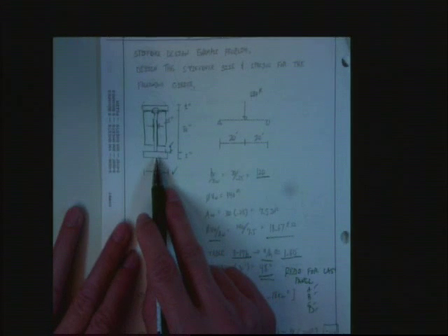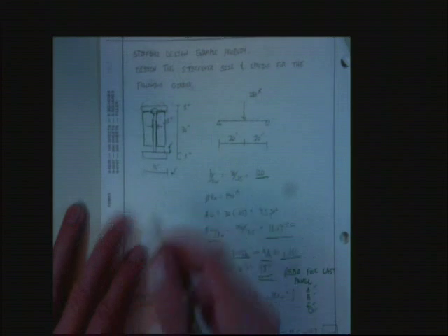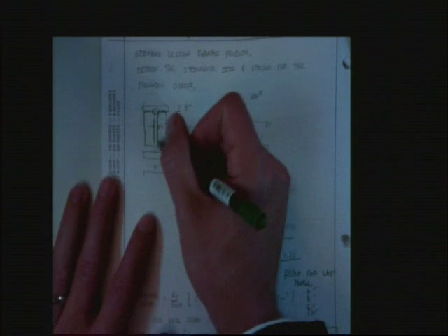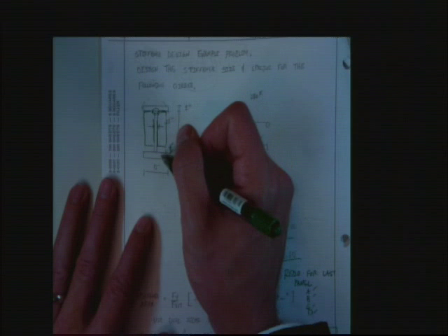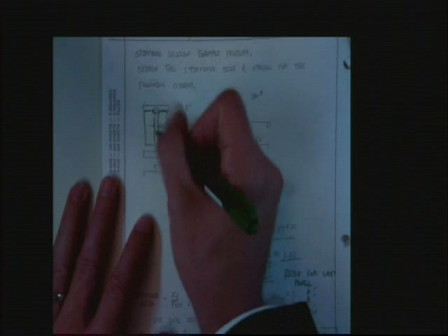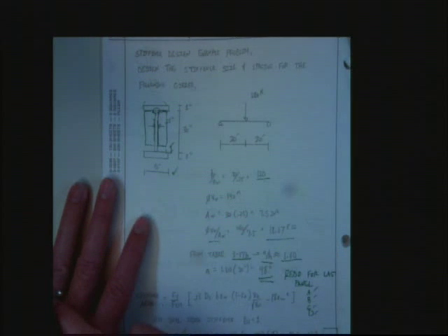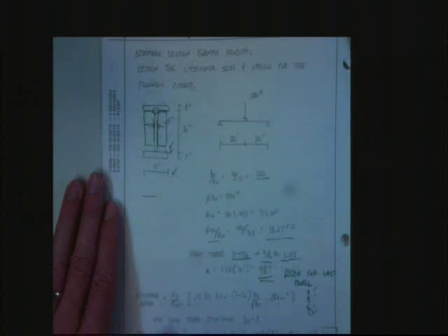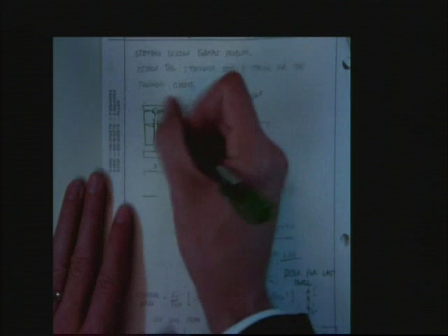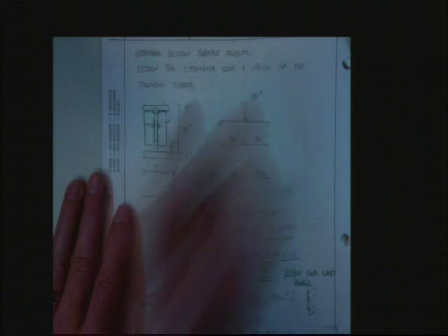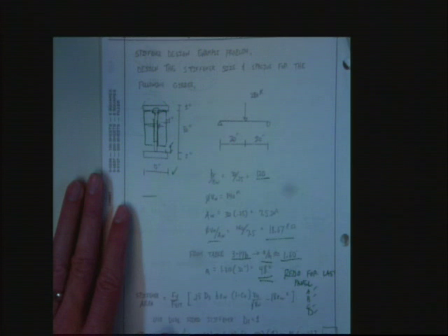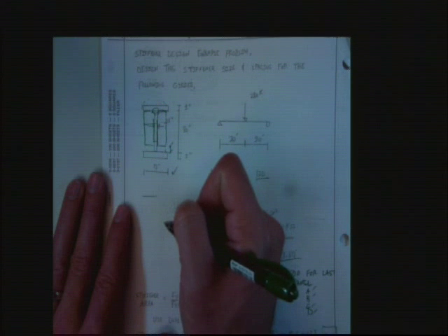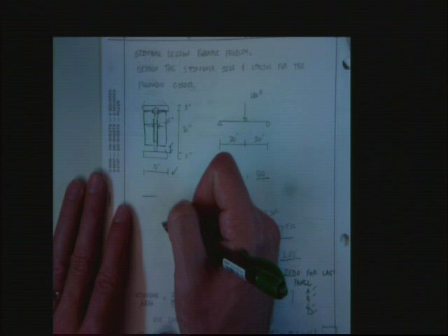Now, was there something else people wanted to say or ask about this? You asked about height. You always have to think about what the stiffener is for. This stiffener's job is to keep the web from buckling. So it would be totally wrong to leave that stiffener very short because it could still buckle below it. In that case, you're going to want to go at least past the 3/4 point of your web. But you don't have to take it all the way to the bottom. Again, it's important to understand what your stiffener is doing.